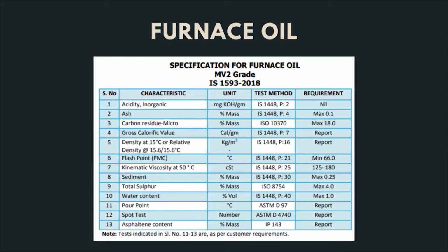So the viscosity is going to be a crucial test, known as the kinematic viscosity. Flash point is important for safe handling and storage of the fuel, and so is the sulfur content. The sulfur content is going to determine the kind of pollutants when the furnace oil is burnt in the furnace. If more sulfur is present, it is going to create a lot of emission, and finally you are going to pollute the atmosphere.